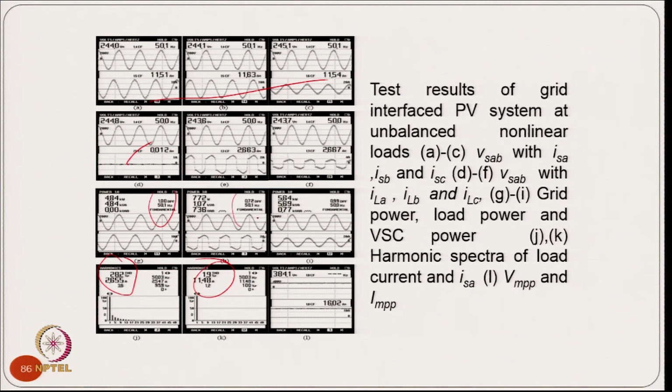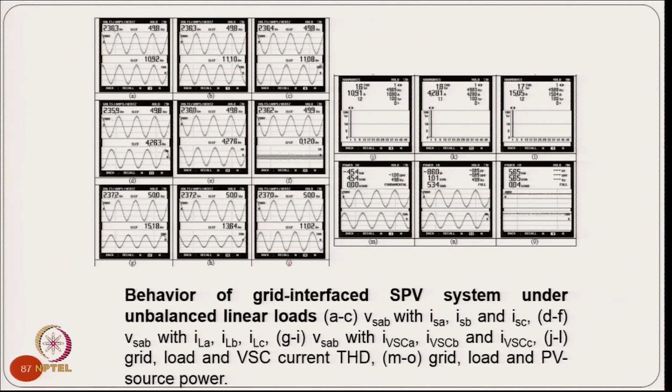In spite of the load power factor being quite low, about 0.72, it gives load balancing as well as harmonic elimination. It is compensating the load locally here. This is typically a linear unbalanced load, but the grid currents are balanced,